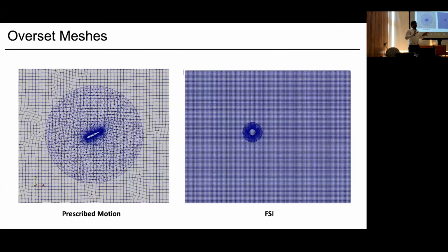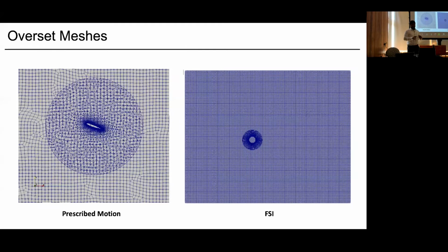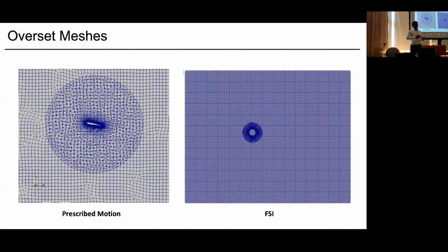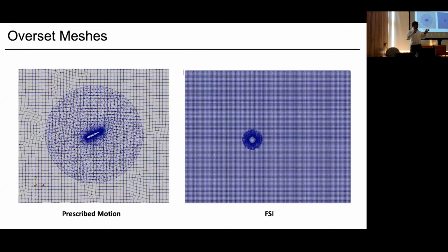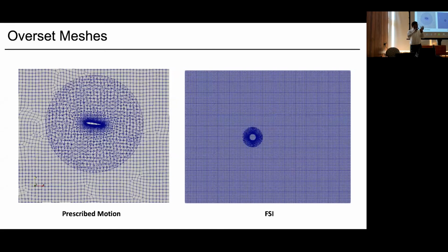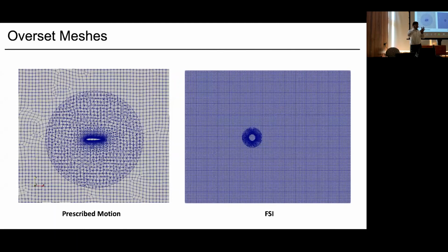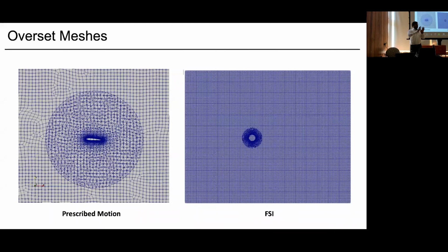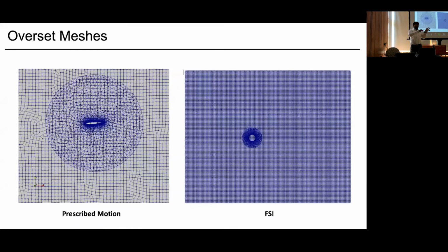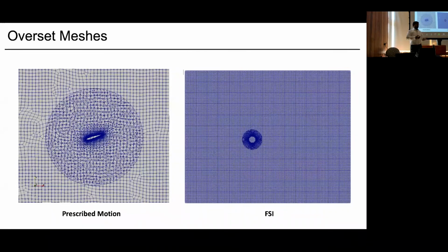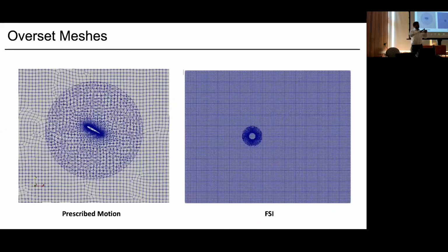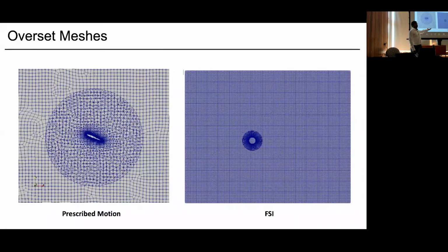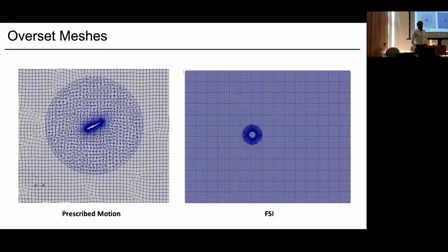And the case files should be separate, which I probably did not mention here explicitly. I would plan to show you, if time permits, that for overset cases, each component mesh has its own case file: zero, constant, system. You first import the mesh there, and then you merge it with the background mesh with the function called mergeMeshes, and then you have the meshes merged together, right? And on the left-hand side, this cylinder case is generated in blockMesh, so it's a very easy structured mesh.